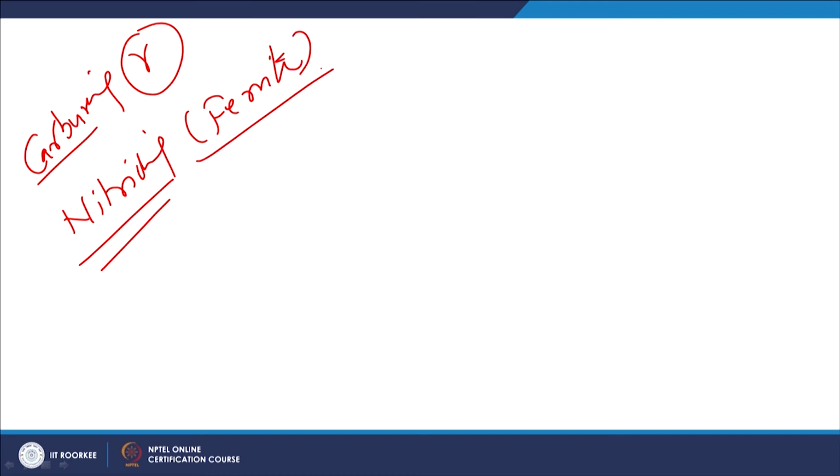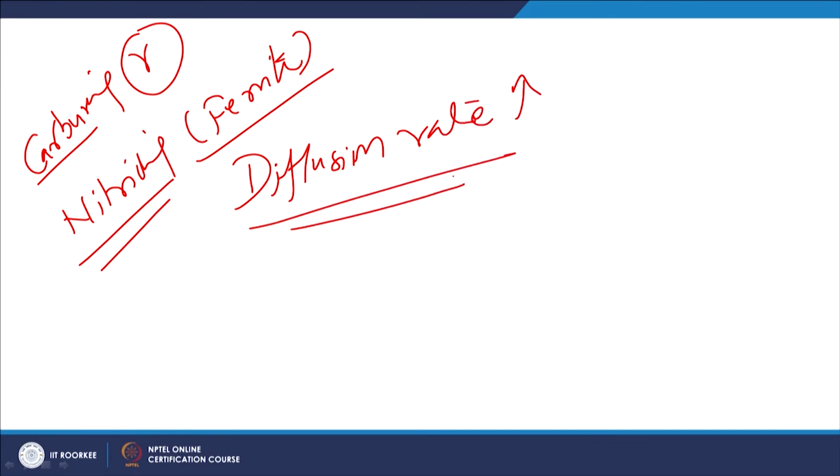So, the steel, even during nitriding, will be in the ferritic condition, and the reason for this is that when nitriding is performed in the ferritic state, the diffusion rate is quite good. So, to exploit this benefit and to avoid unnecessary high temperature heating, nitriding is performed in this temperature range of 500 to 590 degrees centigrade.